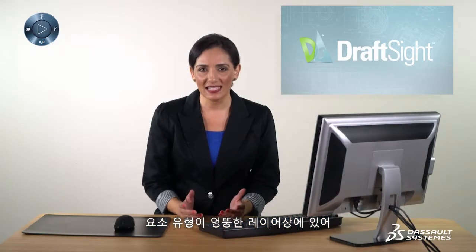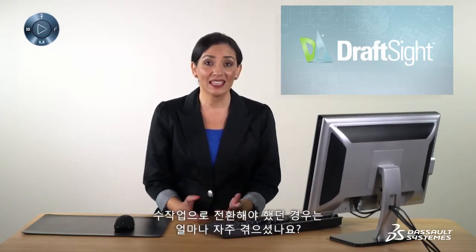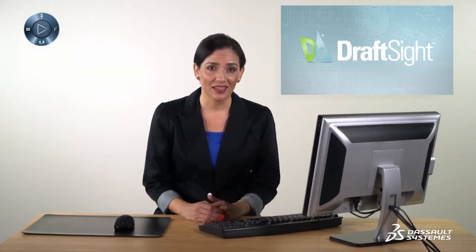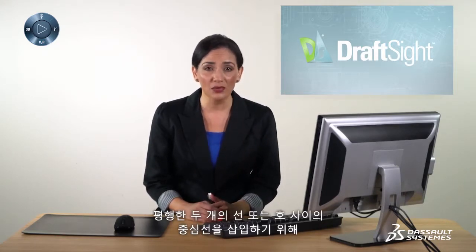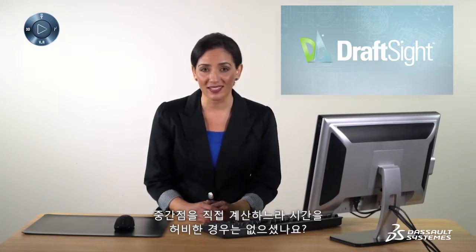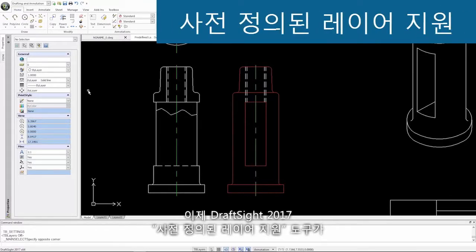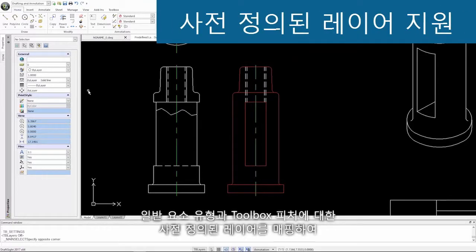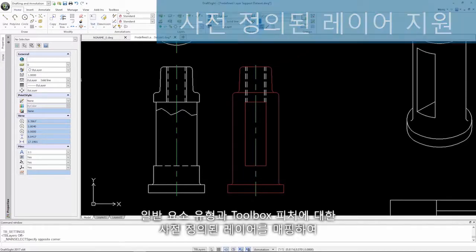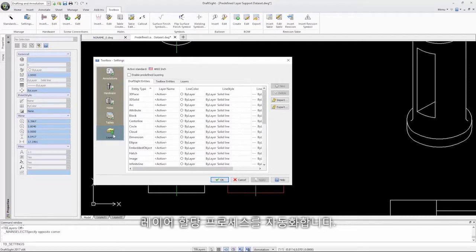How often have you had to manually switch layers between different entity types because they were placed on the wrong layer? What about wasting time to manually calculate a midpoint in order to insert a center line in between two parallel lines or arcs? The DraftSight 2017 Predefined Layer Support tool automates the layer assignment process by mapping predefined layers to common entity types and toolbox features.